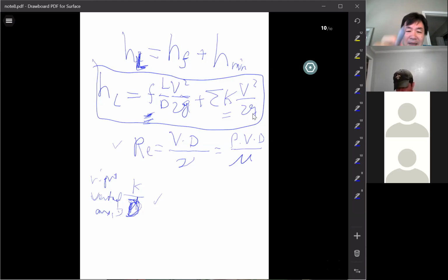Okay, this is the Moody diagram. So now we know how to calculate. In a practical piping system, your task is to identify the overall loss. Very important. You need to know how to identify the overall loss for a piping system. The loss has many components in your piping system. If you have a practical, very complicated system, you have 20, 30 components, maybe different pipe sizes in the whole system, and you have different f too.